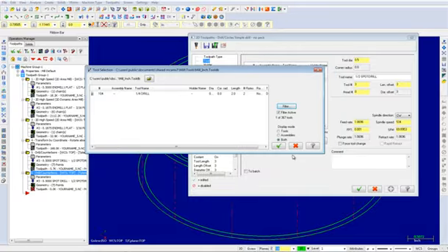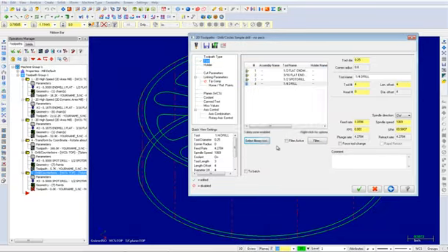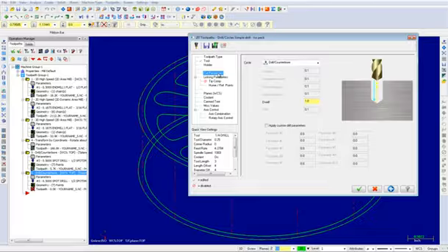You will now see the 1/4 inch drill. Select this drill and choose the OK button. Your drill will appear as shown. Input the following comment: drill the holes. Select the cut parameters. This time, change the drill cycle to chip break and input a first peck value of 0.1 as shown.